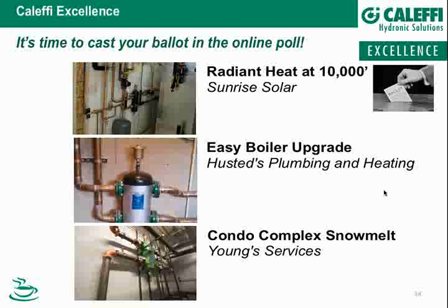One that I've seen of late is controlling a Delta T across the boiler. We've been doing more work with some of the wood pellet boilers and the wood gasification boilers, and they can actually operate at a pretty decent Delta T. You don't have to limit them necessarily to a 20-degree Delta T. So if you want to operate at, let's say, a 30-degree Delta T, a circulator could be set up to do that. And the advantage is you're going to use less pumping power.